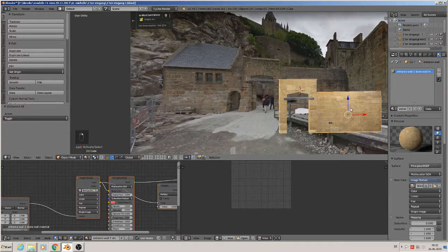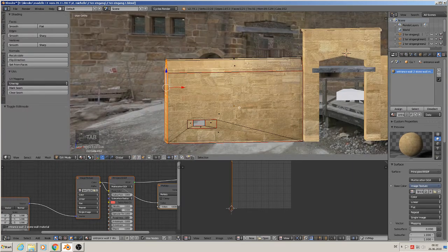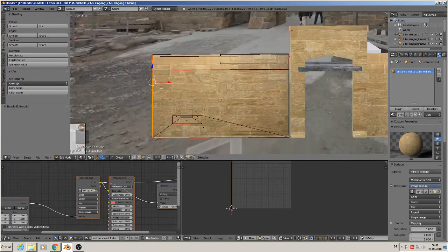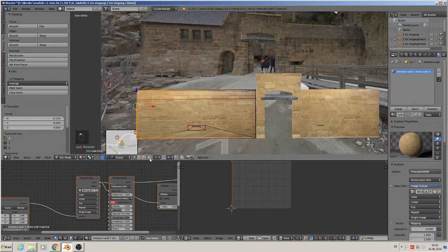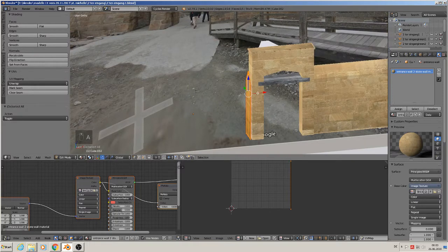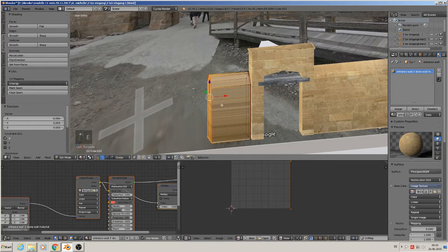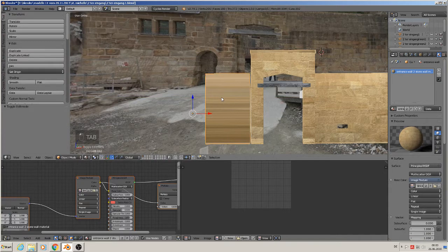So we take that wall maybe and delete all the left so we have only that last, and extrude that simply till there. So we have that wall there and cut in there this door. Good. We have changed it, so object apply rotation scale.